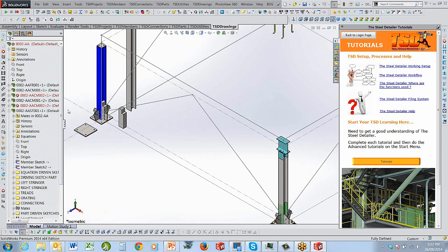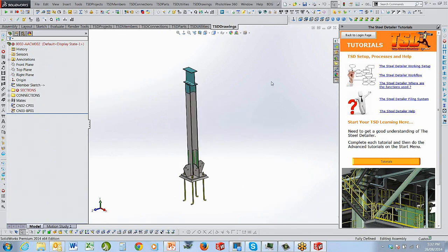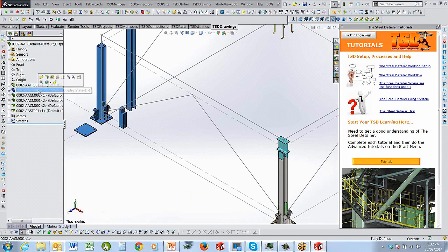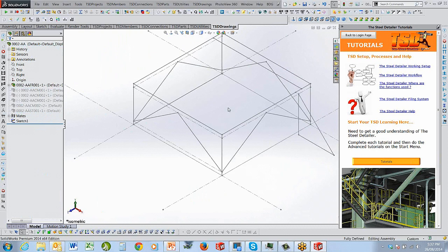Okay, so you just go down into the lower level assemblies and open them up and just do a rebuild, and that fixes it. In SolidWorks 2012, you used to be able to do that with no problems, but for some reason they've stopped a particular rebuild from occurring at a lower level. But that's okay. You just go into it.